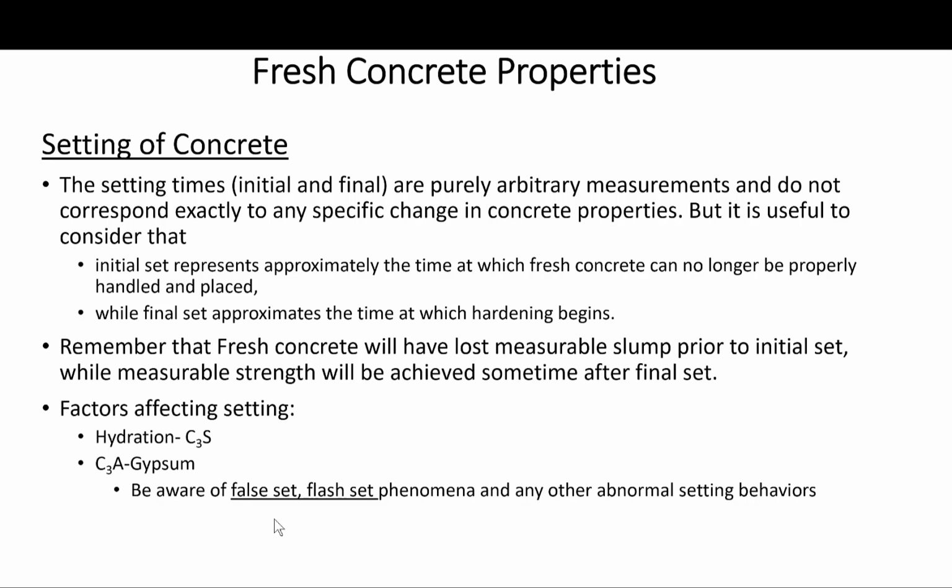So basically, that's something again that you need to be aware of about the chemistry of the cement you are using, and whether the C3A to SO3 ratio has been correctly proportioned in order to prevent such behavior. And again, I said these problems are rarely going to happen nowadays. Nonetheless, they could happen, and it is also good to know the background for such phenomena, so at least you might be able to explain what could happen in any situation. Okay.